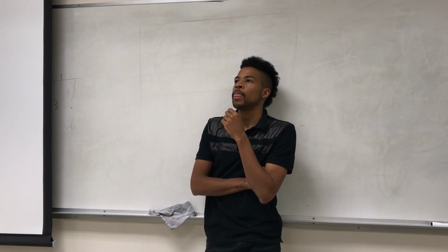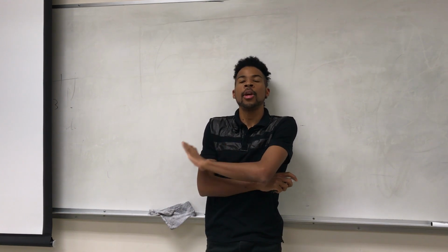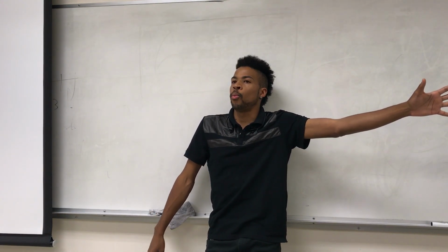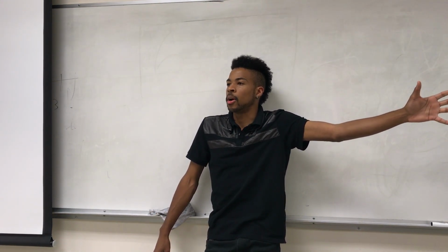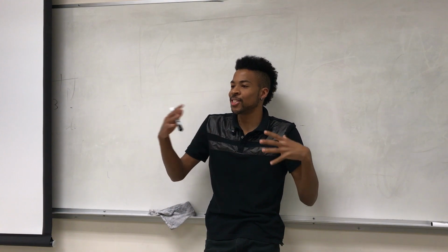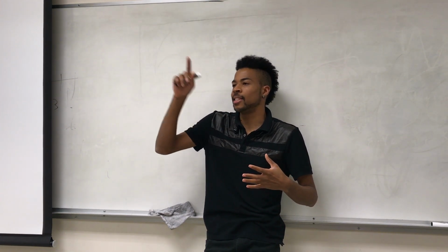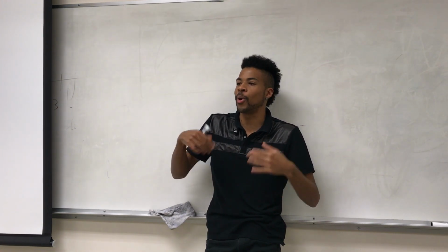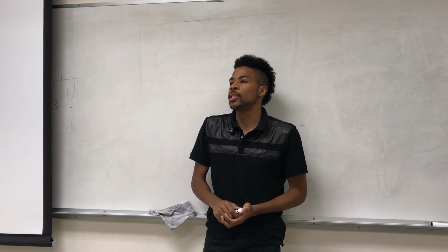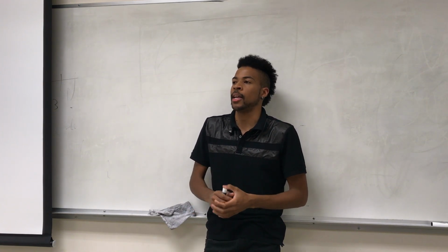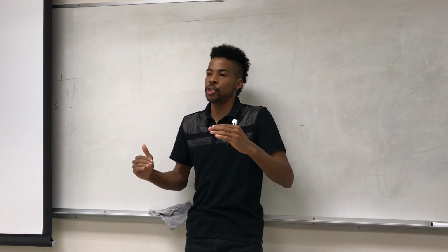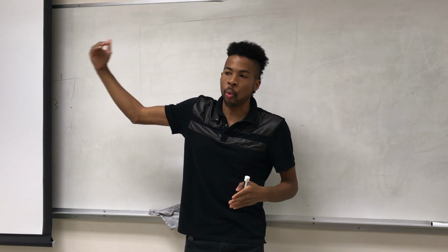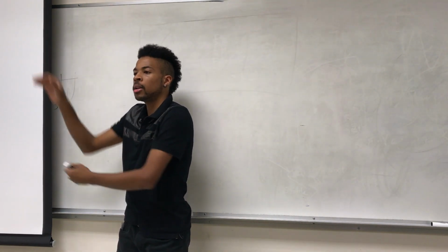Actually, before I go any further, have you guys gone over interrupts inside of the 146 lecture? Cool, you guys have gone over that. So you know about the state machine within the Intel 8086 and the state for when it checks that stuff. A lot of systems will usually have hardware that will just interrupt the state machine and put it over to another spot.